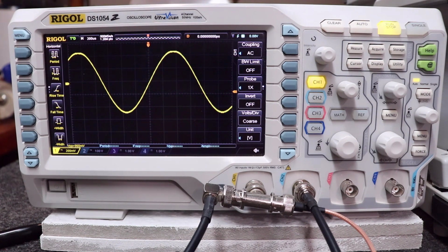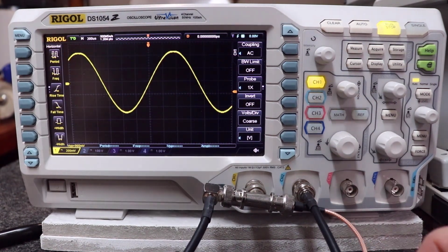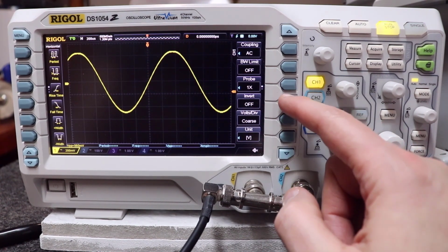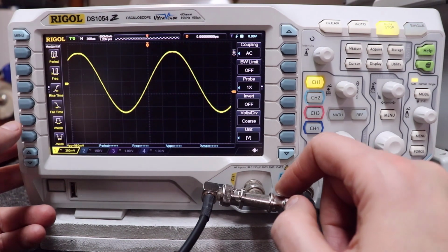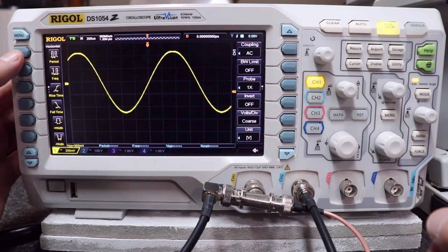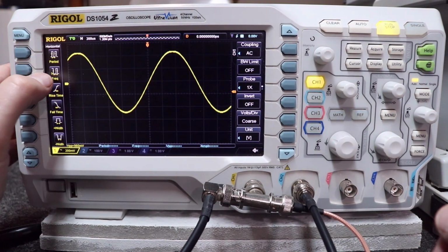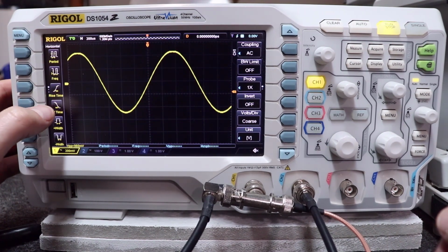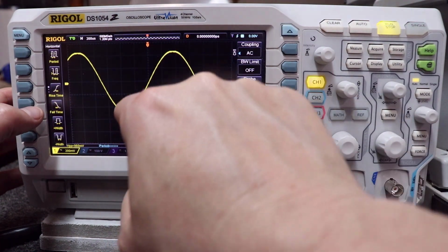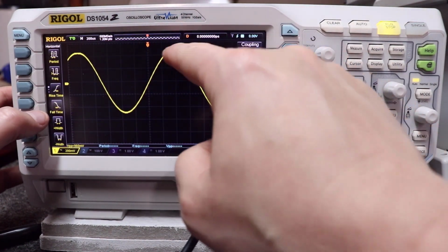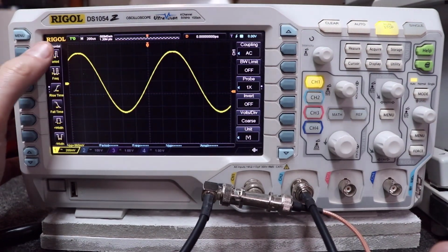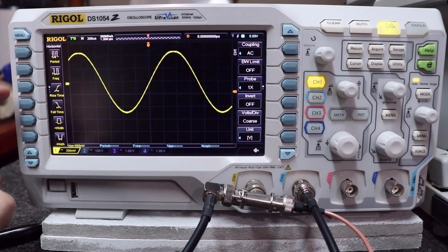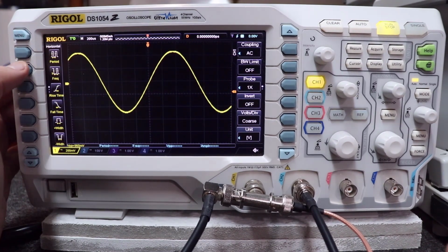So super smart little units. Lets you do, honestly, a lot of things that the unit I was showing you earlier can't do. I can invert my signal. I can limit the voltages. Over here on this side, I can measure period, I can measure frequency, I can measure rise time, I can measure fall time. I measure how long it takes the signal to go from here to here, how long it takes to go from here. I can measure the width of each signal. Lots of measurement capabilities over here on the left just by clicking on this.